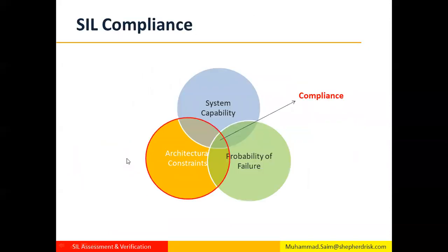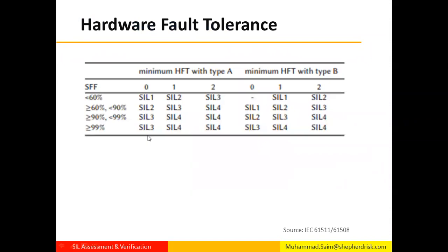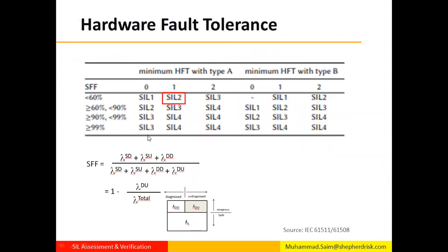But here we have seen that the IEC 61511 architectural constraints require us to have a hardware fault tolerance of 1 if using hardware with a safe failure fraction of less than 60%. So in any case, we will be providing a 1 out of 2 ESD design on our P&ID.